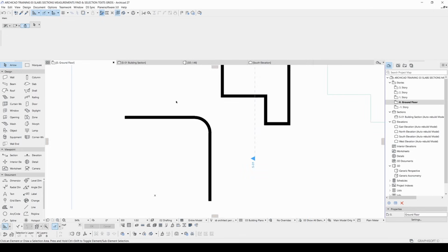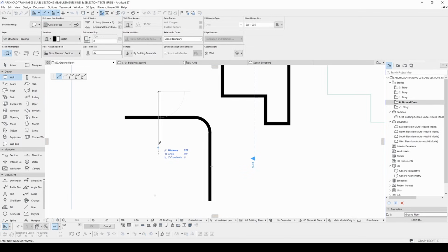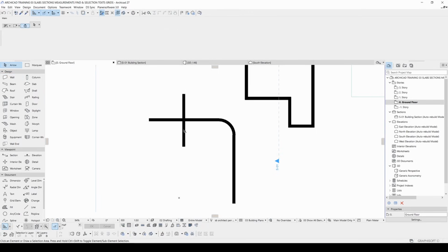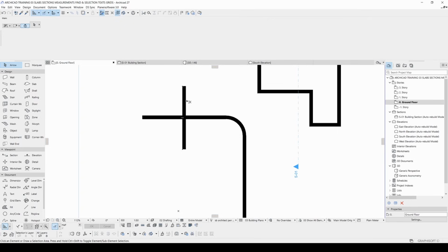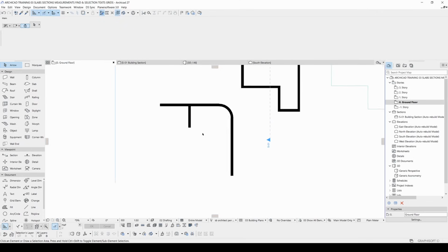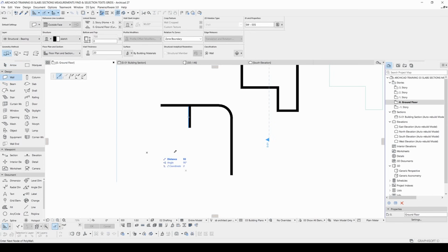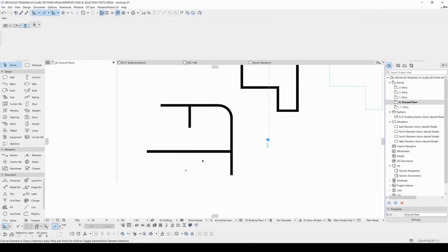Let's create another wall and intersect them. And after that, I'm going to hit Ctrl and click this part. You will see it will trim. Ctrl works for your computer also. It's the default setting. After that, I'm going to place another here, maybe. And I'm going to click arrow, click the wall, and I'm going to click adjust. After that, I'm going to click this. It will work as the extend command in AutoCAD.